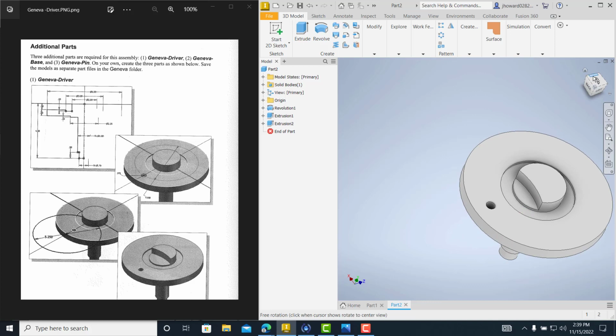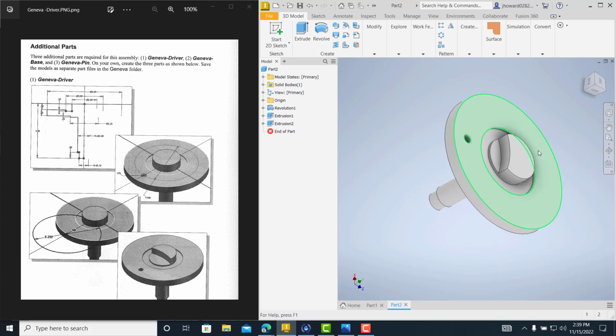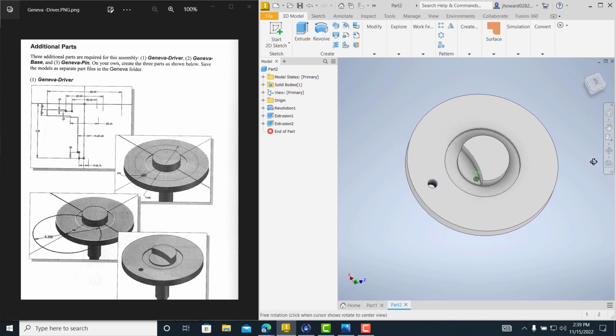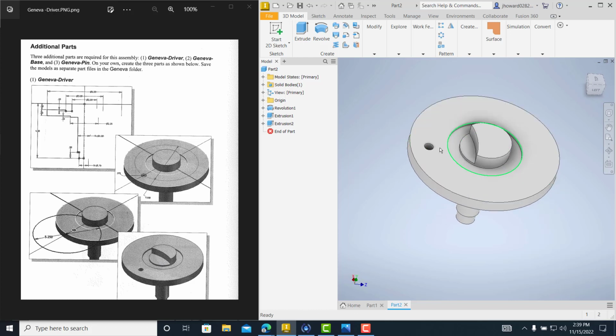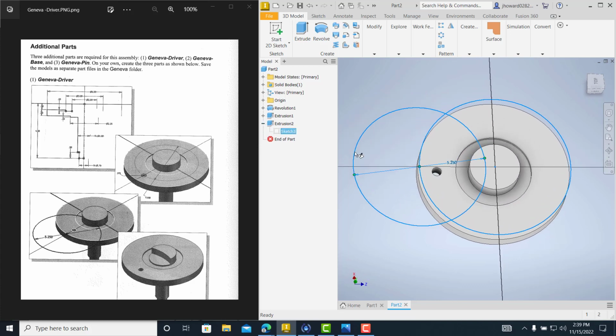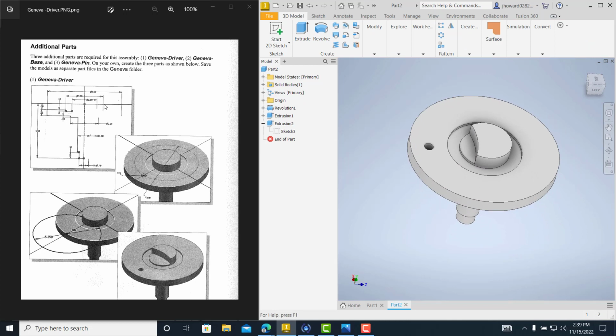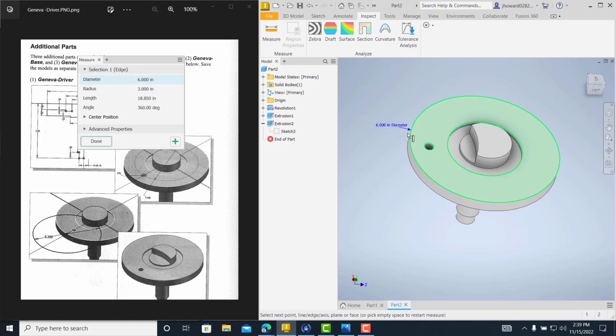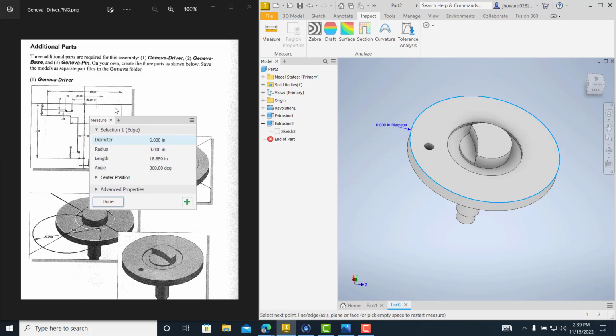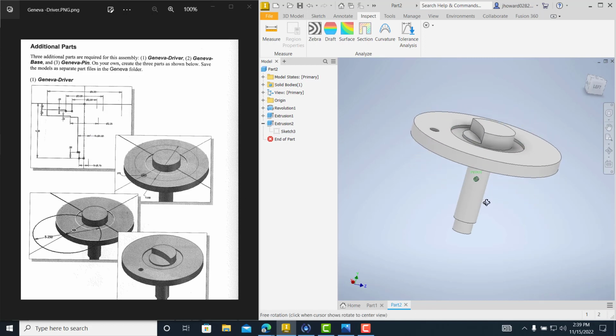All right. So I'm just looking at it and make sure it looks okay. Doesn't look like it's as cut as much as this one for some reason, but it may be just the way that I'm looking at it. So I want to go back and just check myself and double check. Sketch 5.25, that's exactly what we have there. They've got it right at that quadrant. That looks good. I want to check my overall diameter, should be 6. I just want to do a check. Inspect, measure. This is a 6-inch diameter. This is 6-inch diameter. So obviously that has to be pretty close.